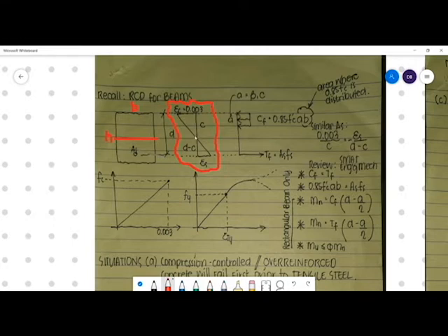So, there is your strain of concrete, which is linearly proportional and measured from the neutral axis. At the neutral axis, there's no stress that occurs, as well as no strain. And the distance from the neutral axis to the extreme compression fiber is letter C.